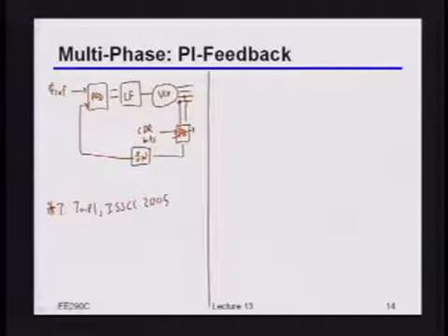Can you keep muxing between certain phases? Okay, you could do that. You could basically pick one phase on one clock cycle, and on the next pick a different phase. You could indeed do that, and that actually does work. Although that has the unfortunate characteristic that, because you're generating these big jumps, you then have to make the PLL sufficiently low bandwidth that it filters those jumps out, right? So you could do that, but unfortunately that has some not so good implications in terms of the PLL loop bandwidth.